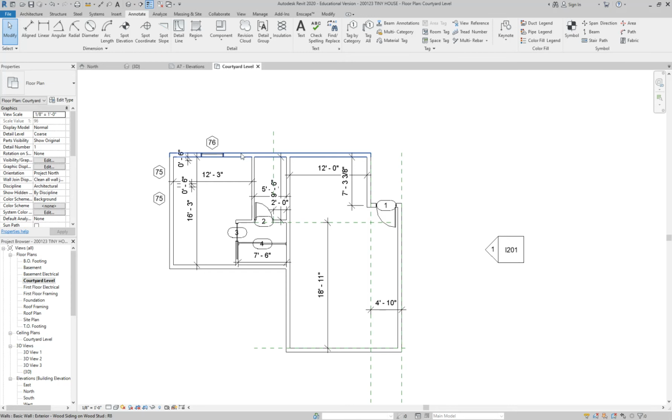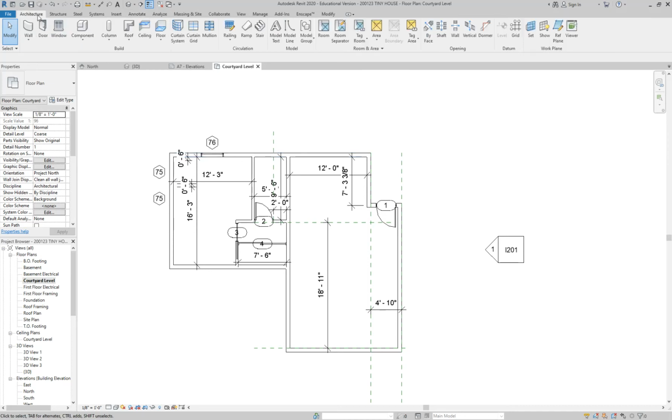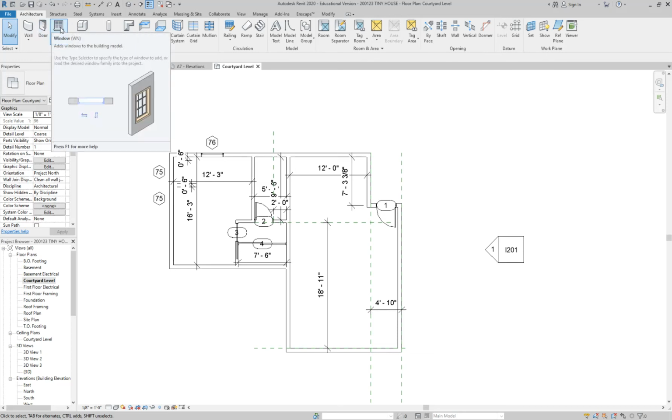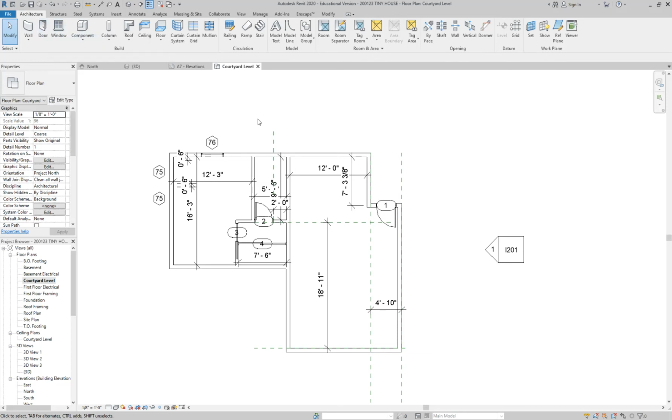And then we had a couple more shortcuts. I didn't write them on the board last time. Sorry about that. So I made a note to go over them today. To put in a door, you can go to the architecture menu and click door, or the shortcut is DR. Window is WN. We already know that wall is WA. And then the last new shortcut that we did was AL. I think that was actually from the previous class, but I didn't go over it on the last set of questions, so I'll go over it this time.